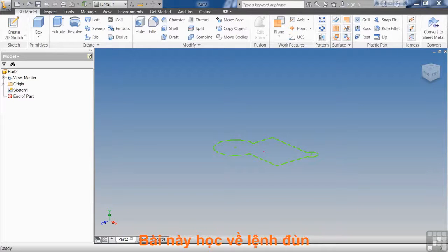In this exercise, we're going to be discussing creating extruded features. Use the extrude tool to create extruded features from existing sketch profiles. Sketch-based extrude features require an unconsumed and visible sketch to be available. If the sketch contains a single closed profile, that profile is selected automatically whenever you start the extrude tool.